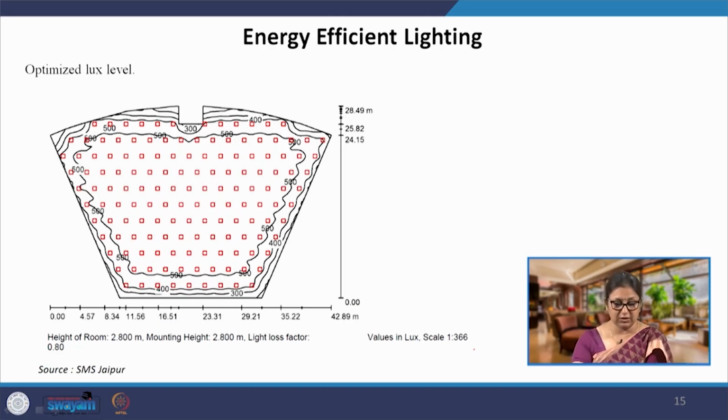If you look at this particular example, the space has been designed and the way these luminaires have been provided is to have the minimum, the threshold illuminance that has to be provided, the lux level that has to be maintained for the given space and for the given activity. So, first step, we design the space and the windows. Second, we select the luminaire, and third, based upon the luminaire we design the artificial lighting, we distribute it uniformly.